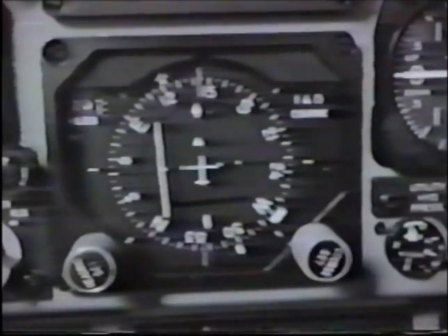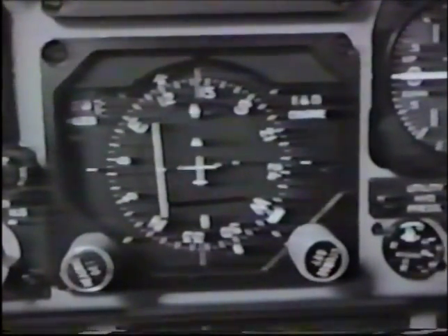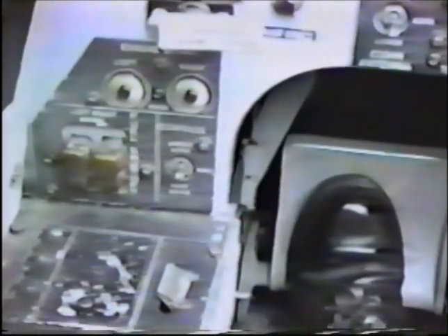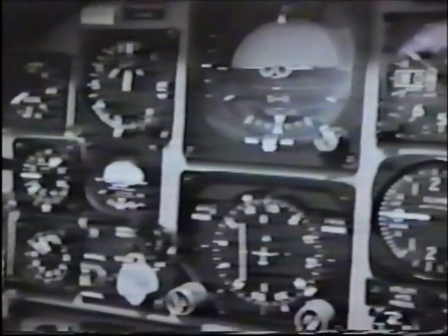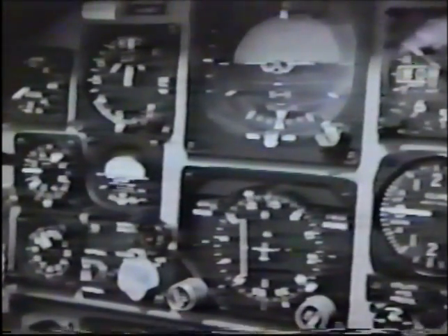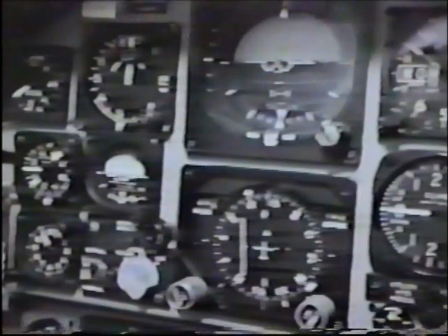To begin the navigation check, look at the heading on the HSI and cross-check it within 8 degrees of the magnetic compass. If the headings do not agree within 8 degrees, move the compass switch to fast slave momentarily. This will begin a 30-second slaving cycle and should align the heading on the HSI to within 8 degrees of the magnetic compass. When fast slaving, avoid taxiing the aircraft until completion of the 30-second slaving cycle.